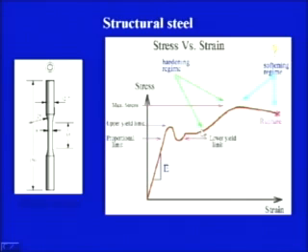the microstructure here is already set up. So now there is a permanent deformation existing. Here there is maximum hardening. Once we are getting the maximum tensile strength, that means once the object offers the maximum resistance, beyond that it loses its hardness. So this part, in which the object is not offering the maximum resistance, is known as the softening region.